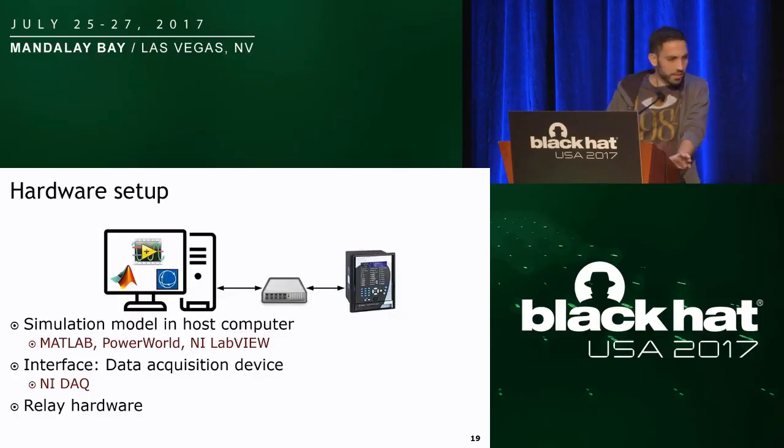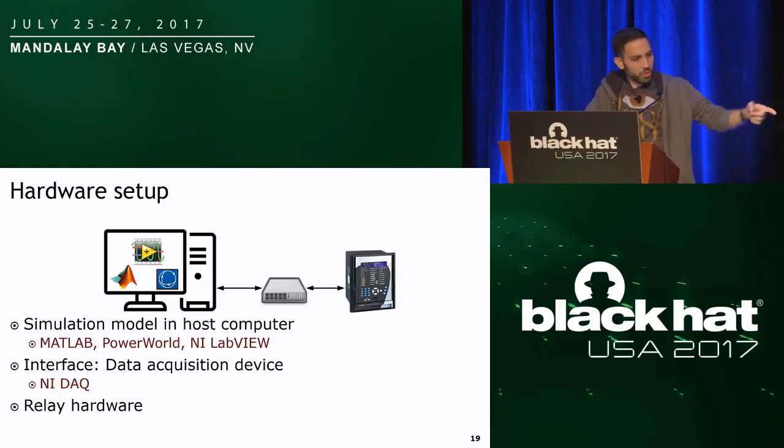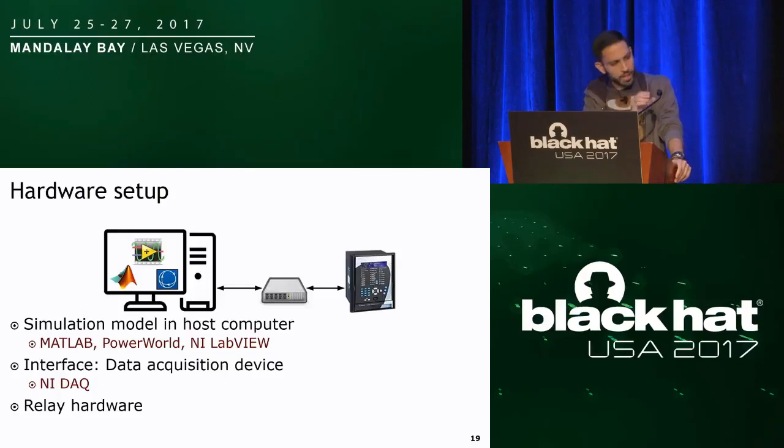So in our case, in this setup here, we have a hardware-in-the-loop simulation configuration where the simulation model resides in the host computer, which is the laptop over there. And it runs the synthetic model that we showed earlier in PowerWorld. The circuit breaker connections are achieved via MATLAB and LabVIEW in order to connect the actual hardware relay, through a data acquisition device, to the simulation model. So with this setup, we can have realistic studies without the need of replicating all the expensive and bulky equipment.